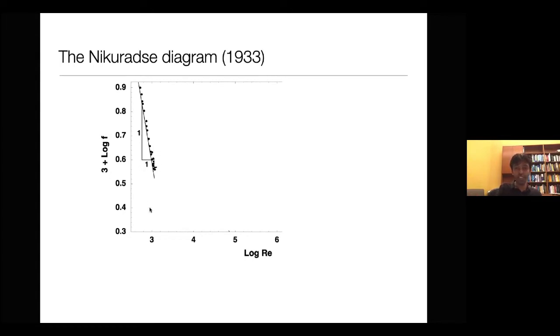But when you reach a Reynolds number roughly of the order of 2000 or so, then suddenly this friction behavior changes completely. Instead of decreasing as 1 over Reynolds number with increase in Reynolds number, friction flips over and starts to increase with increase in Reynolds number. Initially, this increase is still collapsed onto the same bundle. The friction curves corresponding to the 6 different roughnesses are on the same bundle.